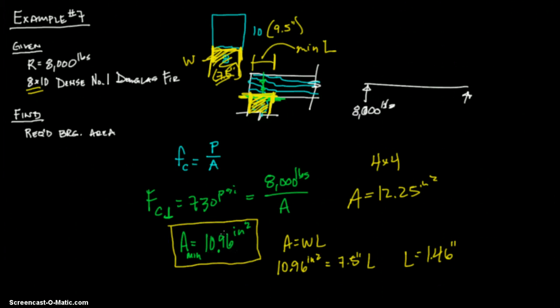10.96, you're not going to get a piece of lumber that's exactly 10.96 area to fill that timber post underneath. In real life, you know what I do? I go 8x8. Call it good. Then you get plenty and plenty of area to give.